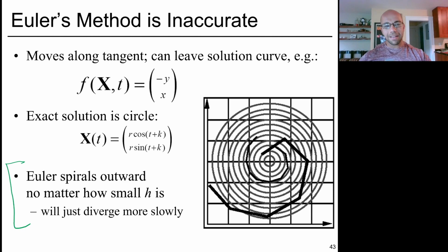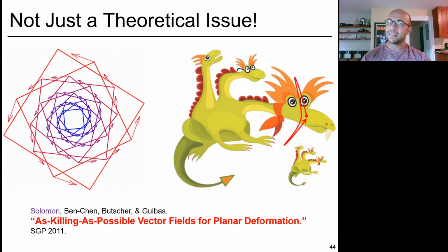Why does that matter? Let's say that I'm including a physical simulation component in a video game. I don't know how long people are going to play the video game. If I leave this game on its own devices and just sit there and wait, and I'm using Euler's method, it'll slowly add energy, and the game might slowly explode. So you have to add some hacks to tamp down the motion and counteract that. In fact, here's a screenshot from one of my own research papers where this became a problem. In this work, we were trying to come up with a method for elastic deformation.